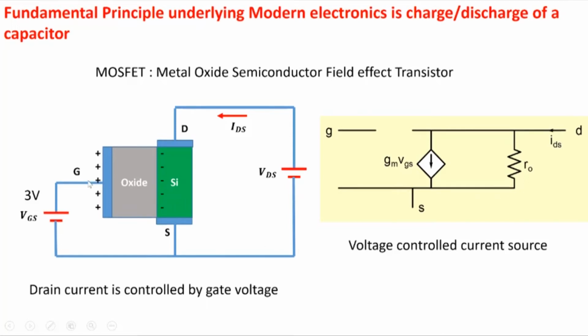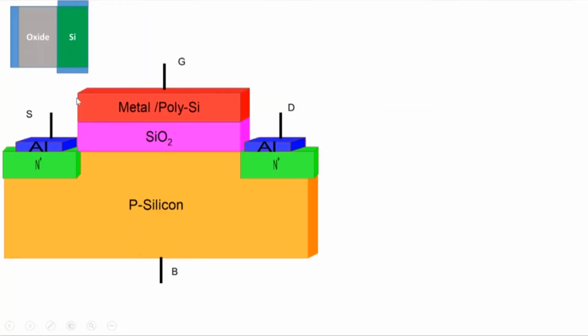So we are saying that the capacitive action, or a capacitor, is a fundamental part of a MOSFET. And this is the symbol that we use for a MOSFET, right? So gate here, and the gap between the two indicates, say, the insulator, and there's a drain and a source here. The arrow is used to differentiate which one is source and which one is drain, so it allows us to highlight that.